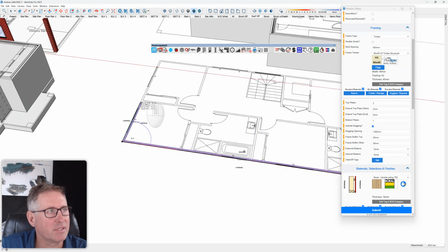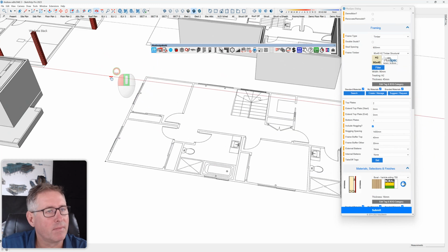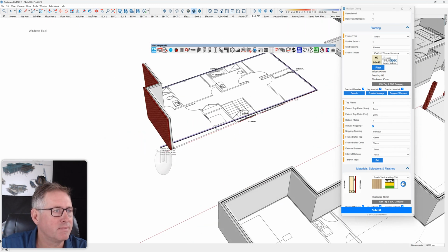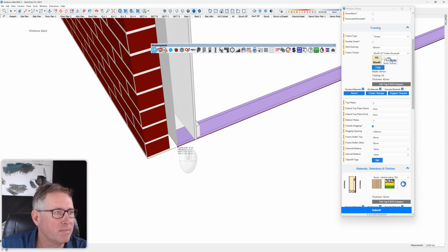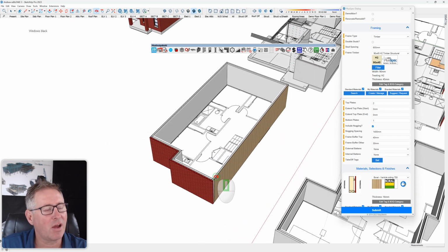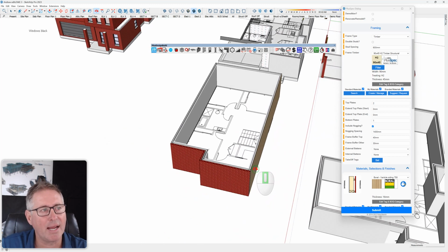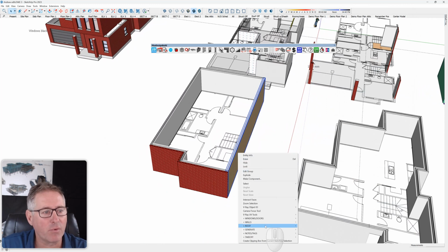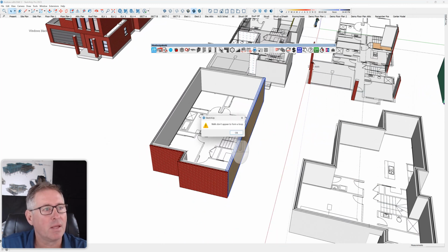Go and trace the rest of the drawing. Go around to where I want it to end, which is here. And now I have two different wall thicknesses on it. The only thing that will create any issues is that if I went right click, roof, create roof from walls, the walls aren't a loop, and they're not a loop because they weren't drawn together.